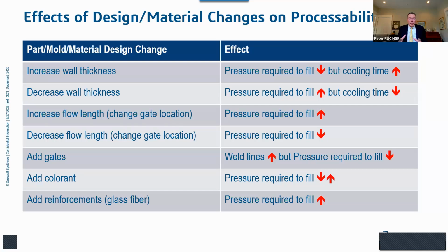So now I'm going to have to make sure that I don't exceed the maximum injection pressure capability of my injection molding machine. But since I made my part thinner, it doesn't take as long to cool. That's going to decrease my overall cycle time. This list could go on and on and on, but here, jumping to the bottom, if I add colorant to